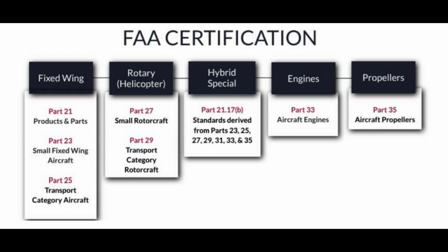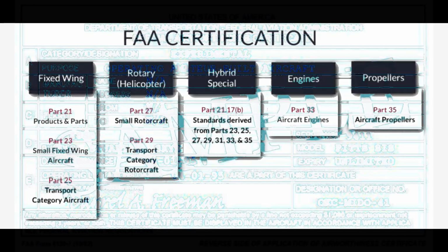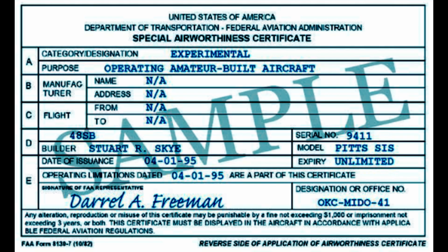The FAA issues a type certificate, TC, for the product when they are satisfied it complies with the applicable airworthiness standards. When the TC is issued, a Type Certificate Data Sheet, TCDS, is generated that specifies the important design and operational characteristics of the aircraft, aircraft engine, or propeller. The TCDS defines the product and is available to the public from the FAA website at www.faa.gov.